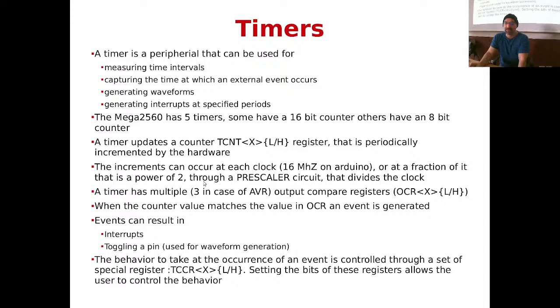Then, in addition, another register that you have is a control register that is called timer compare control register or whatever it is. And then once again, you have a digit that identifies the counter. And then once again, given that it's a 16-bit register, you can select the lower or the highest part of this register. Okay? Then also we have another thing attached to a timer, which is a register that